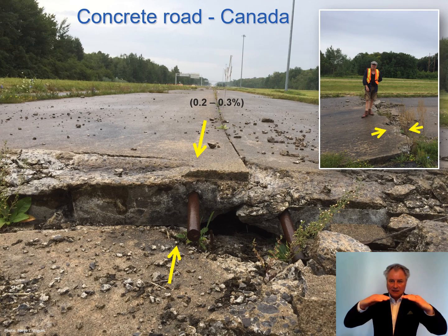That means that the concrete is expanding and the joints are just exploding in a way. So you can see that every joint has been pressed together, pressed too much together, so that the slabs have been pressed up. So this is the effect that could happen if you have a reactive composition in your concrete, and the expansion will continue like this.